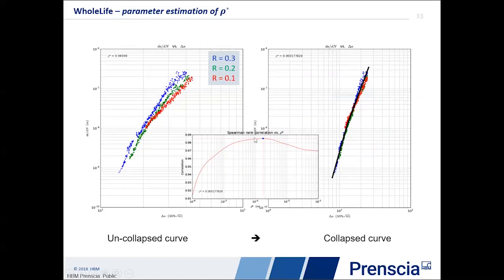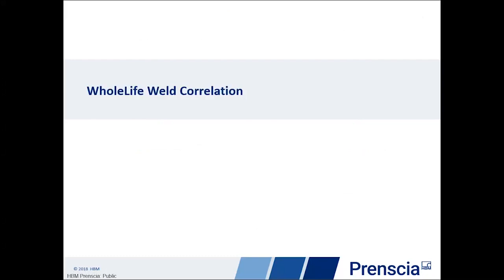So this Rhostar, this initial crack size, and again, the crack increment that we use to initiate through, is part of this material fitting parameter. So we have implemented inside of DesignLife Weld a crack growth procedure that does initiation and crack growth with the assumption that we have this blunt notch at the tip of our crack.